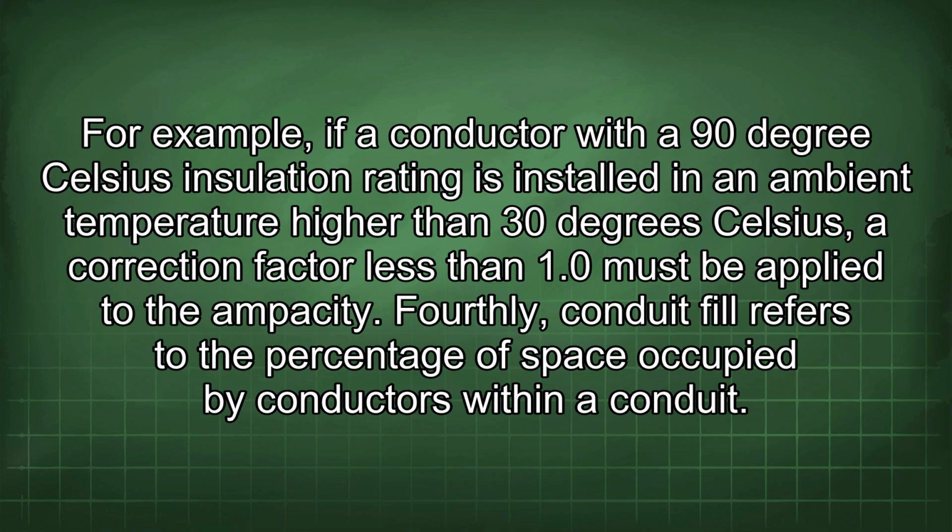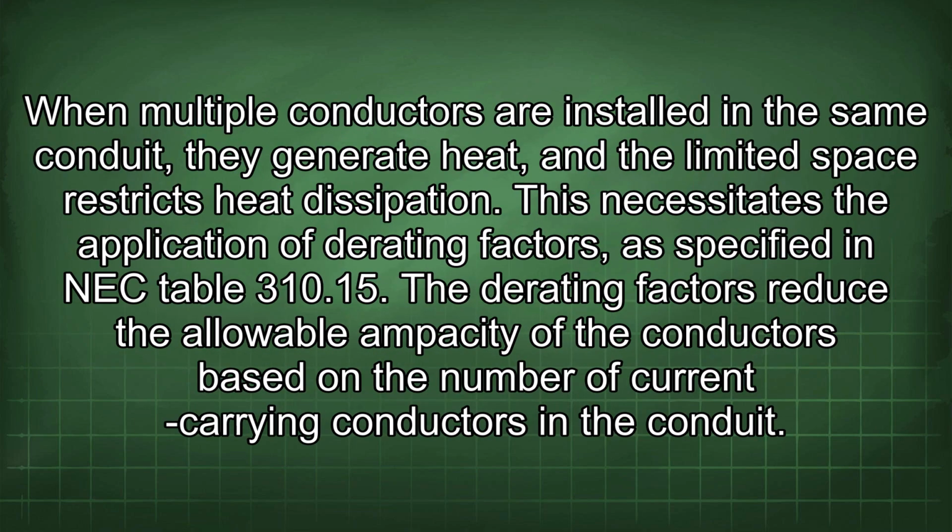Fourthly, conduit fill refers to the percentage of space occupied by conductors within a conduit. When multiple conductors are installed in the same conduit, they generate heat, and the limited space restricts heat dissipation. This necessitates the application of derating factors, as specified in NEC Table 310.15. The derating factors reduce the allowable ampacity of the conductors based on the number of current carrying conductors in the conduit.